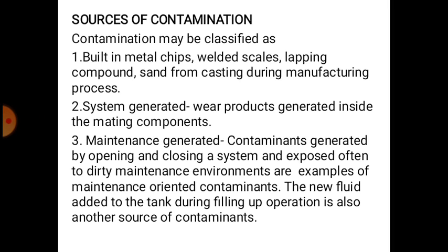Sources of contamination. Contamination may be classified as built-in: metal chips, welded scales, lapping compound, sand from casting, or debris produced during the manufacturing process. Some are system generated, where products generated inside the mating components may be categorized here.